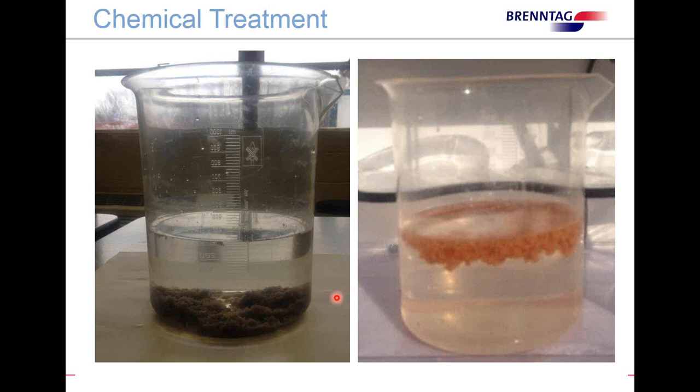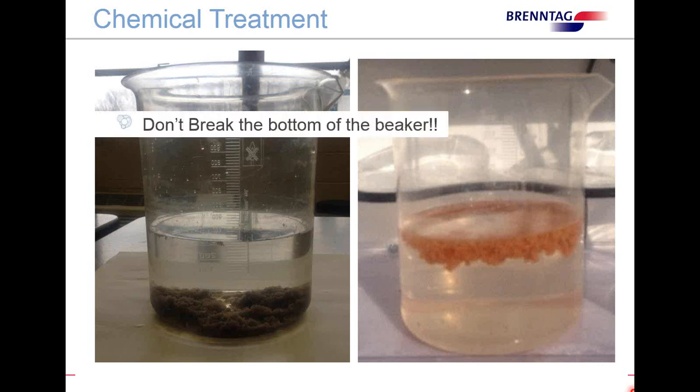But I always like to use a little joke and say, as long as it doesn't break the bottom of the beaker, you might be okay. But when you start getting the very, very dense flock and it's really sinking very rapidly to the bottom, a DAF unit may not be the best choice of equipment. And again, I always like to joke around and say, make sure you don't break the bottom of the beaker when you're running your tests.